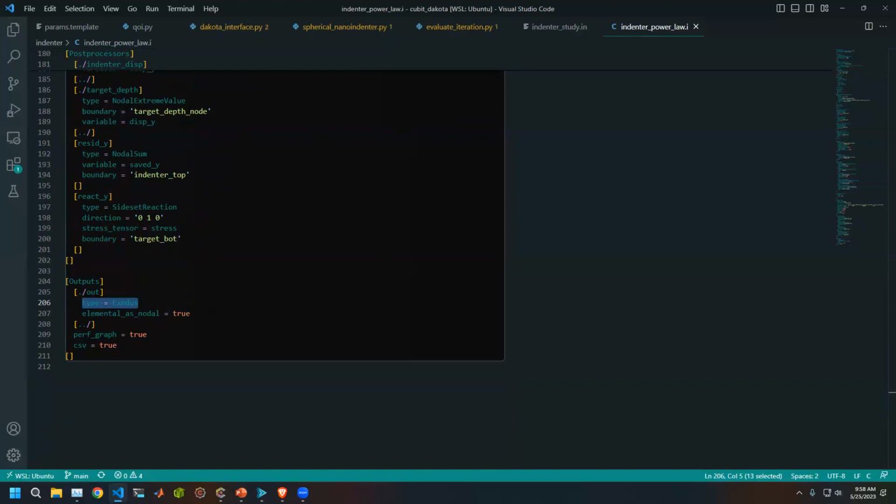In my former lives, when I used to run on HPCs, I would use SlurmPy for submission, but I think even that's now been superseded by some built-in functionality in DAKOTA. So I don't know that I would need SlurmPy today. But yeah, DAKOTA does handle checking whether or not the simulation succeeded. So if it fails, I tell it to just insert a very large objective value and just move on. And so DAKOTA handles that for me.